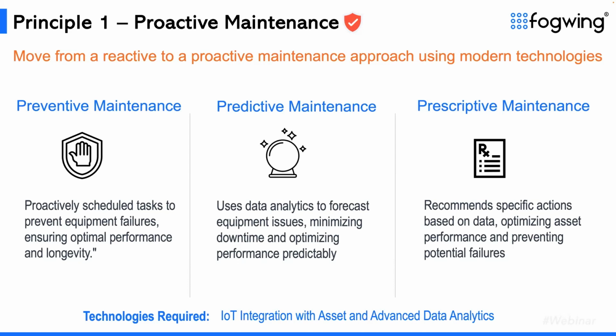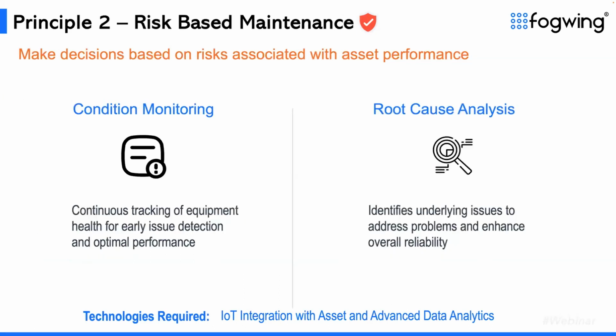We need history data to do preventive maintenance. We cannot just randomly buy a new machine and then do maintenance every 2 weeks. It may not be necessary. We don't know that. So we have to have the history of data. So all of them are important. Data collection from the asset is the foundation to enforce this kind of practice.